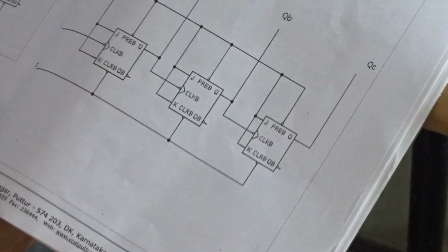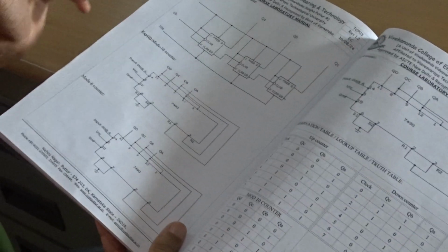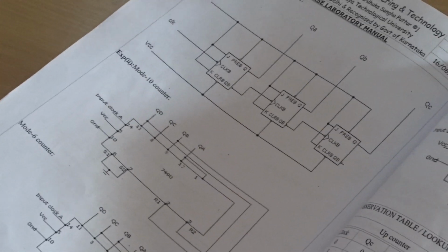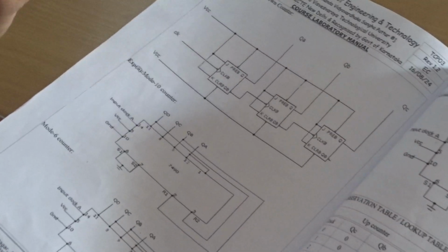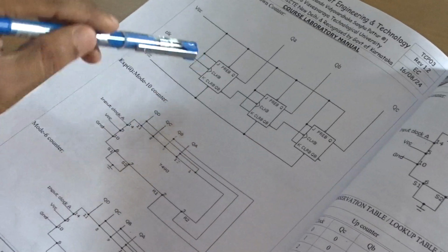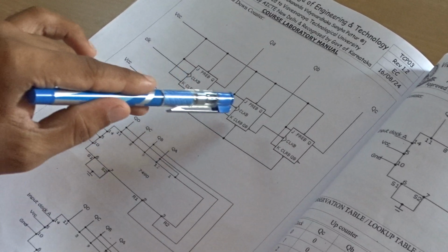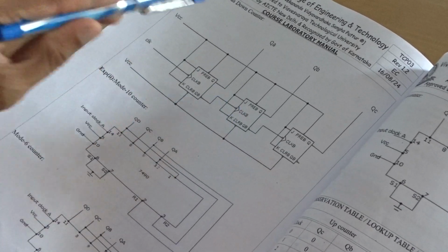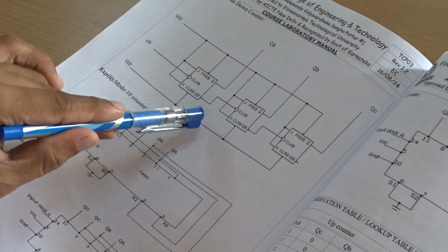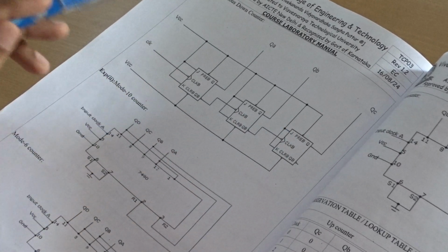The circuit diagram goes like this. For the circuit diagram, again a design is required, and from the design we get these kinds of connections. The asynchronous down counter is also the same, it will go like that, clock, and here also the clock. Here you observe one thing: in the asynchronous down counter you have to give the clock for the second flip flop from the first flip flop's inverted output. So that is what we have fed here, and here also we have done the same.